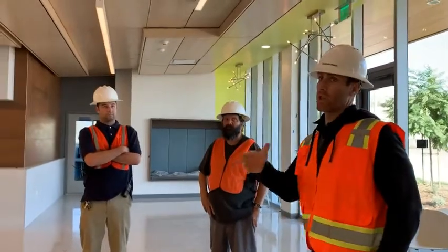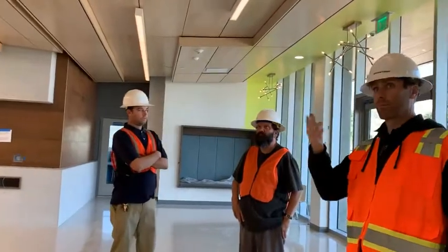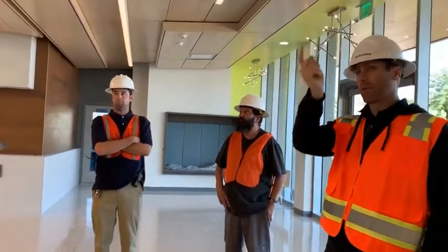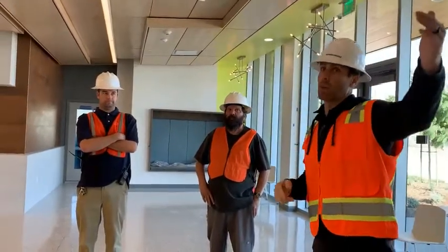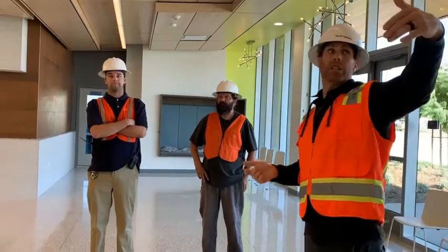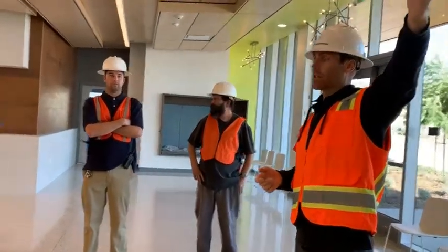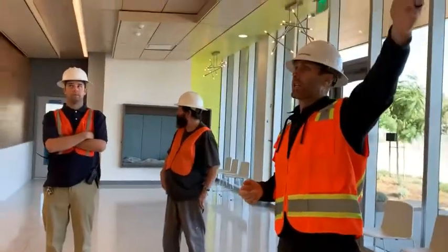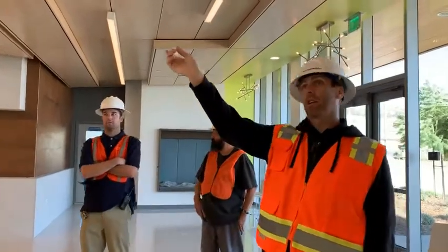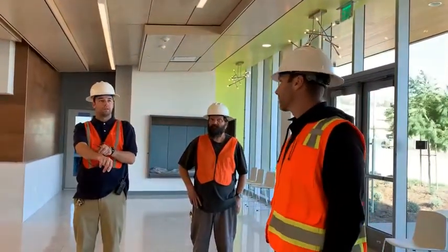But once again, this is no different than everything we talked about. You have your aux sensors in here, because of the type of fixtures they're all going to be relays, and then you have your switch over there. So this is actually one big daisy chain of devices. Most likely your relays are probably back in these rooms over here for access, because there's T-bar and everything. It's all hard lid, and then you'll have just Cat 5 going out to the sensor, and coming back through these sensors and back through any relays and the switch over there.